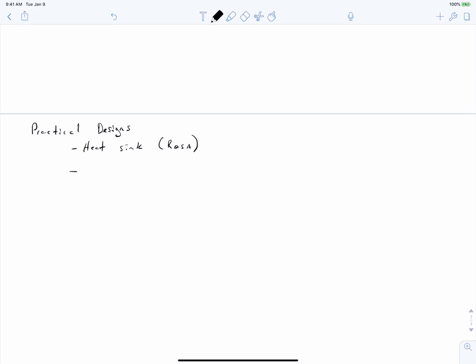And between the heat sink and the case, you'll typically have this isolation pad and perhaps some thermal compound. And that's going to give you a thermal impedance of R theta case to sink, R theta CS. And then of course we're going to be using the case of the MOSFET to extract the heat. So you have a junction to case thermal impedance that you have to consider.